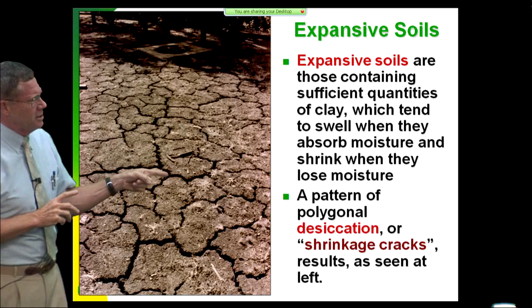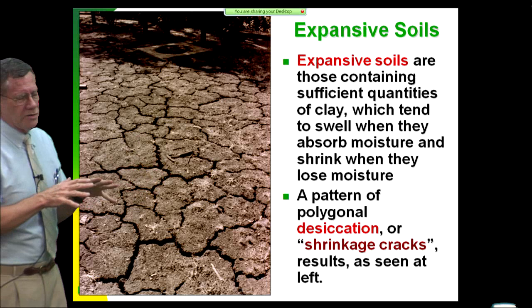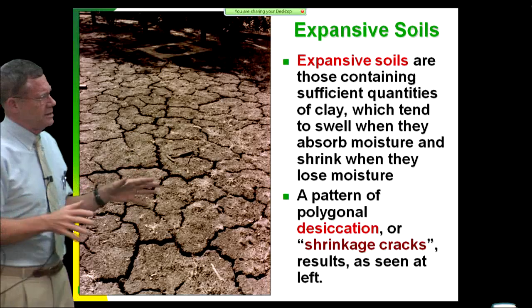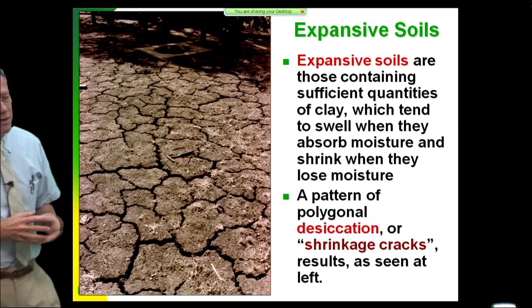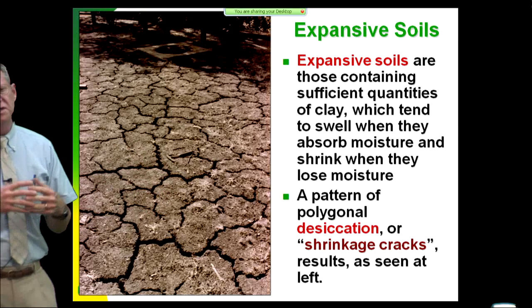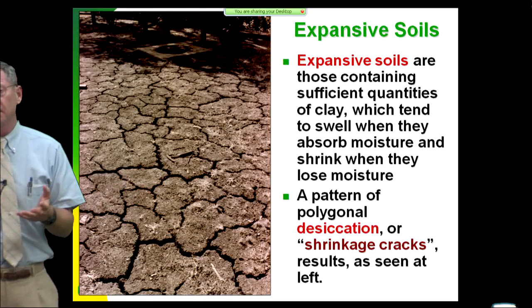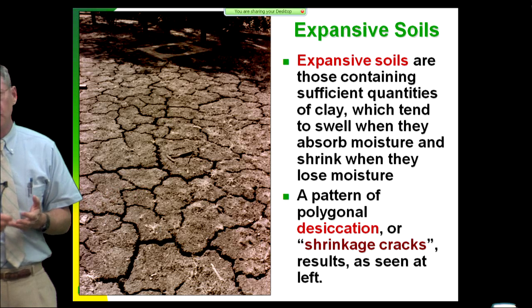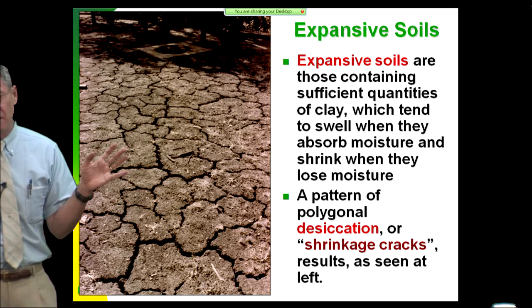But the desiccation cracks are going to be a function of how severe the drying cycle is and what the plasticity of the clay component is. Now, there's going to be very few places where you're going to get pure clay. Most of the sediment on floodplains is silts. But a little bit of clay is going to control behavior. If you have 1% smectite clay, that controls behavior.